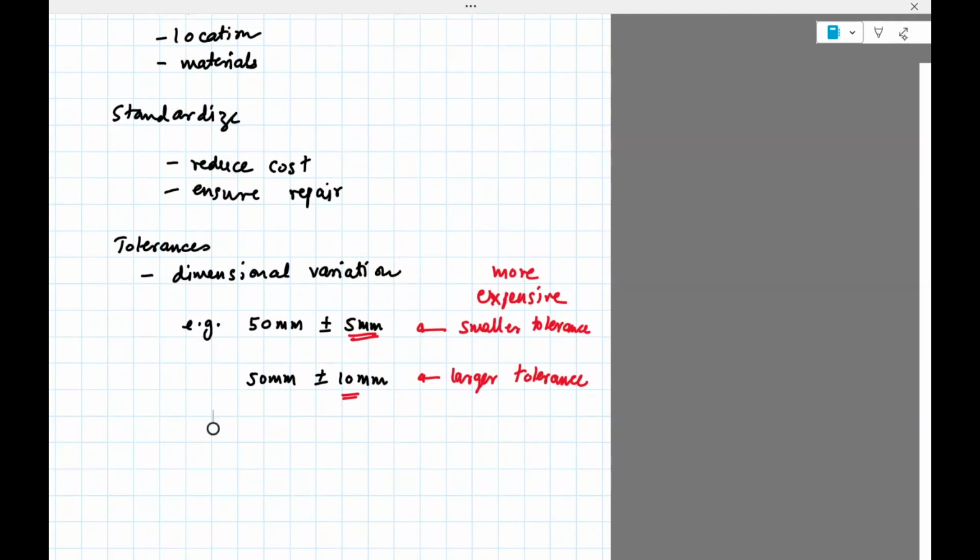Yeah. So when we're doing design with these tolerances and planning on using tolerances, can we just tell the manufacturer +5? Instead of plus or minus 5? You could also have unilateral tolerance. You could have that, yes. This is a bilateral tolerance where you're allowing plus or minus. Yeah, absolutely, you could do that, yeah.